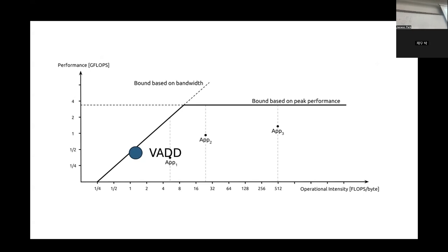And there are 2 reasons behind this. First is that the DRAM is slow, and second is that the application itself has a lower arithmetic intensity. There are applications that have higher arithmetic intensity, such as convolution. In convolution, if you take 1 byte, you will do more than 2 or 3 operations, which means that it will be somewhere around here.